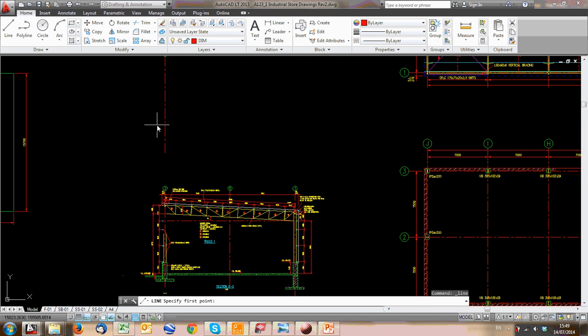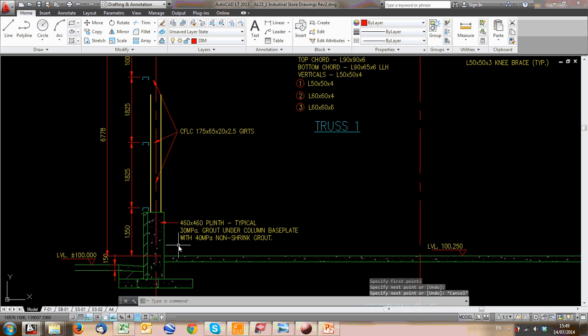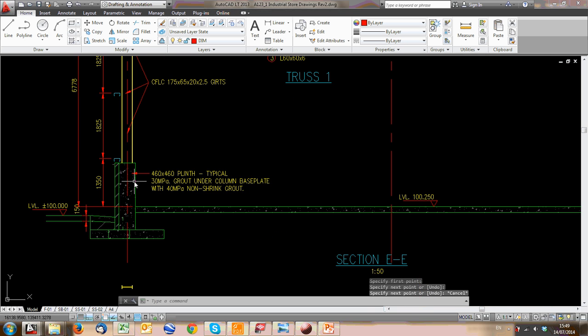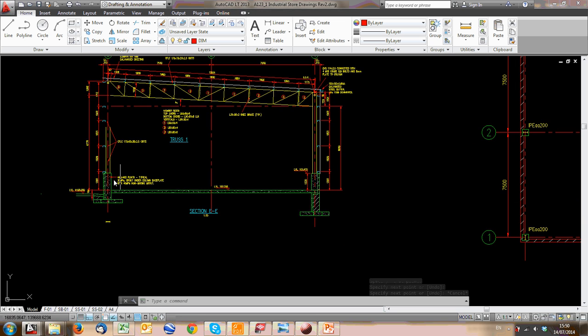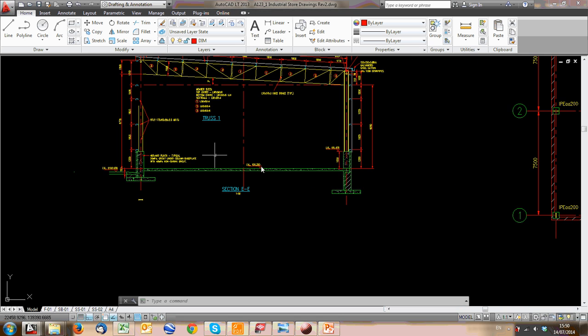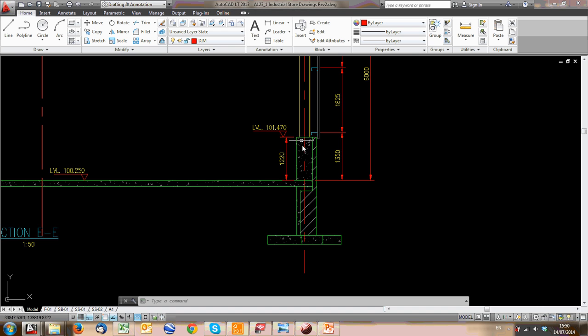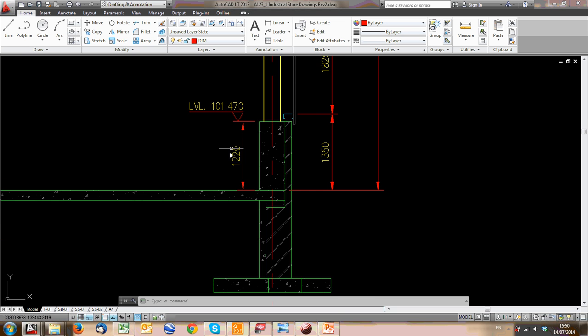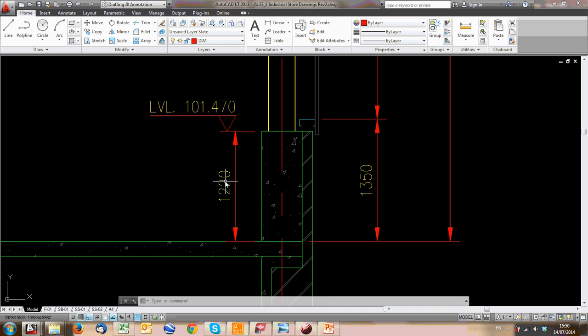Firstly, let me draw an arbitrary line in that will represent the floor. So that's my floor level. How tall must this concrete plinth be? There are different ways to set it out. Sometimes the window will govern it, sometimes various site requirements, ventilation, all sorts of things govern it. In this case, it was just a little perimeter wall they wanted. So the dimension you see there is set out to suit the size of bricks, because that is 1220 millimeters. This is actually 13 courses of brickwork with a roller course on top.